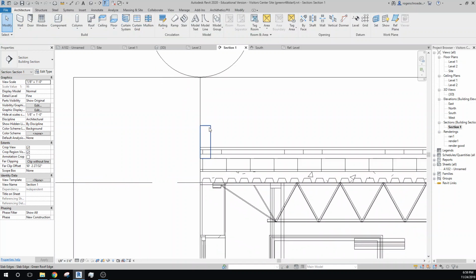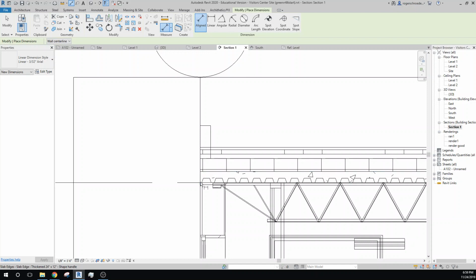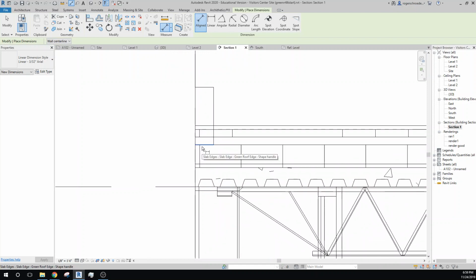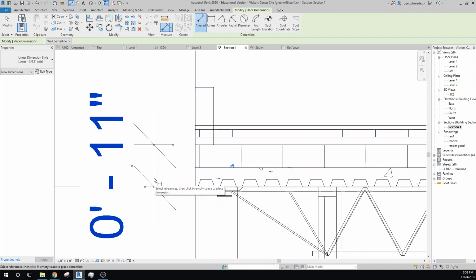And it comes up nice and high, but we need it to come down to basically the bottom edge of the roof assembly here. So what I want to do is measure something here. I'm going to go to annotate to grab the measuring tool and go from the bottom of the profile, and I want to come in here until I'm right at that roof. So we really need to move down 11 inches to cover the edge of our insulation in our roof system.